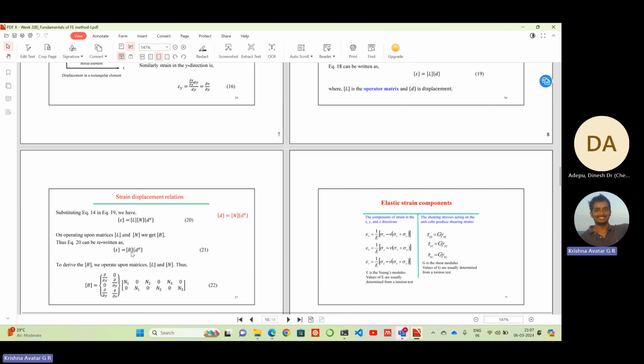No matter which finite element book you pick up, you'll always find B written, because these notations were introduced by Bathe. Yes, K.J. Bathe, at MIT. He's the one who introduced all those notations. Then others also followed, Zienkiewicz, Taylor and all. They kept those conventions. That's why we recall it as B. B is something that just relates displacement to strain in linear elasticity. It relates nodal displacements to the strain.